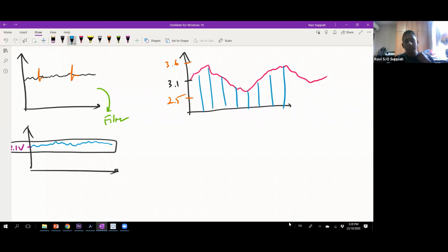What you will see is most of the sample values will be almost the same. Why? Because this range here is too small. This again relates to the way the ADC operates, the resolution and all these things, which is beyond what you need to know. But when the signal itself is very, very small, that means it occupies a very small change in the magnitude. If I try to do a sampling of the signal, all these values will be almost the same, maybe 1 or 2 bits only difference. So you are not able to capture what is really happening.